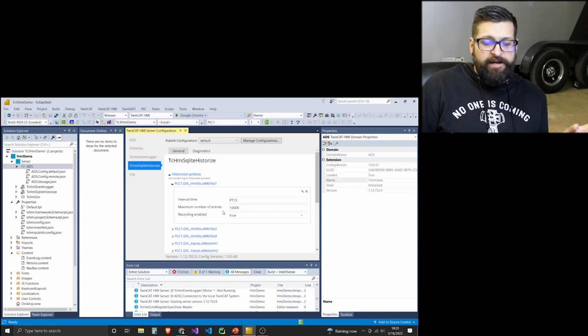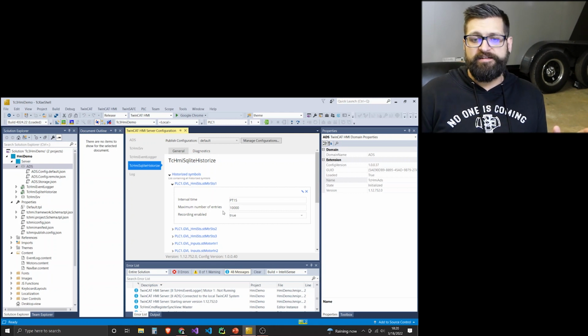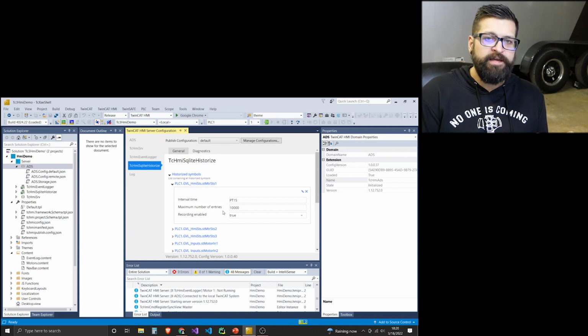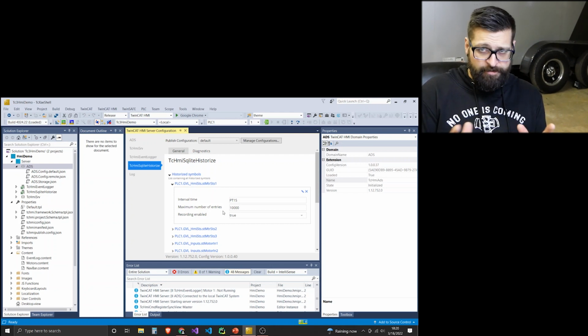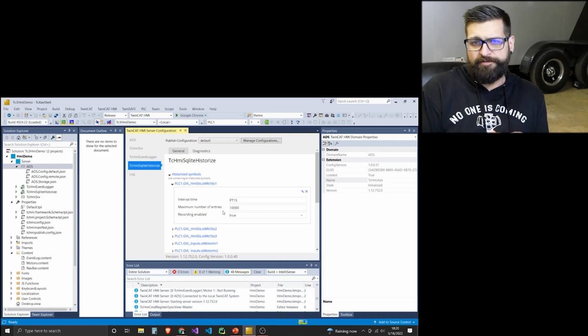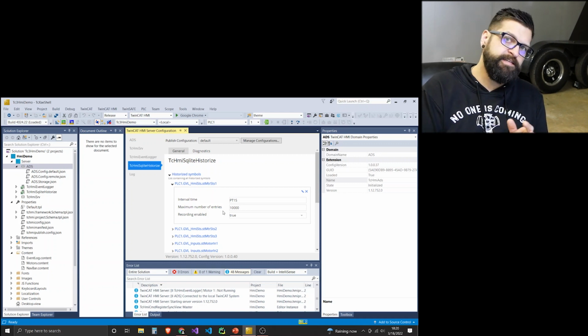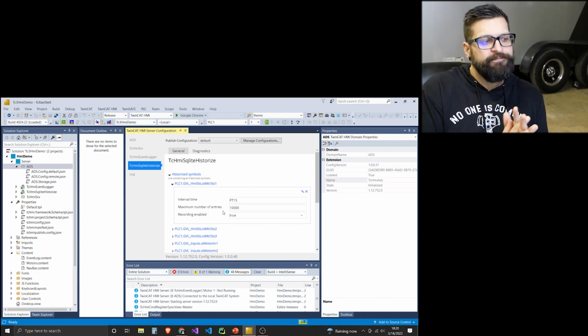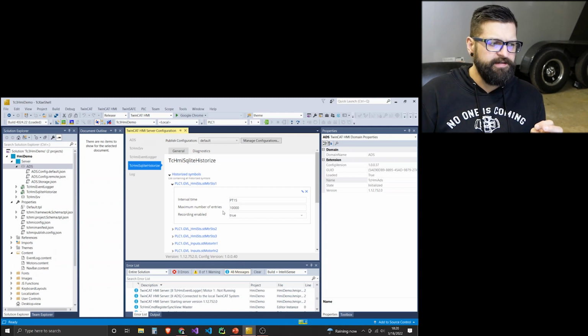These kind of parameters you need to tailor to the capabilities of your system because, like I said, a lot of times these are OEMs that are building front ends or web applications for a specialized machine. If they're using exactly the amount of hardware, CPU power and RAM that they need to get the cycle times and the data processing that they need, you need to be careful about how much overhead you're getting tied up in saving historical data, because this is a ring buffer and it is using RAM. So it's just something to think about as you do this.